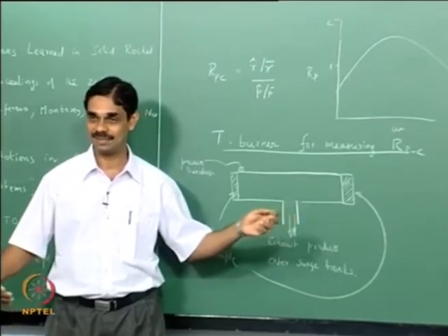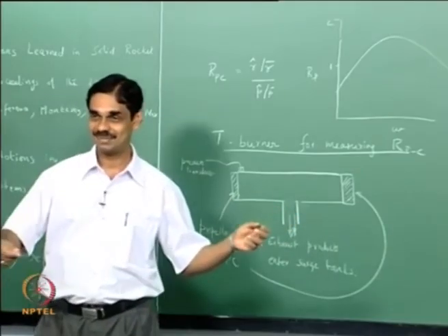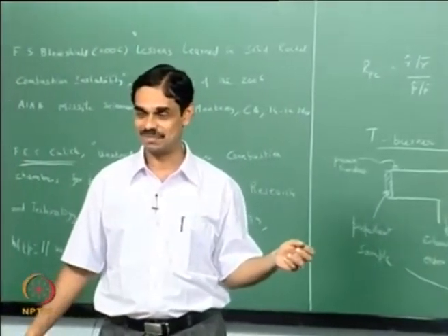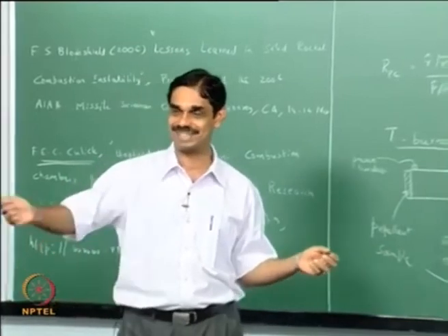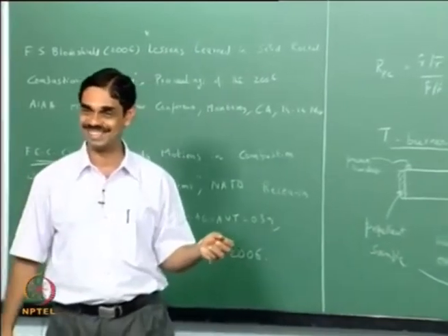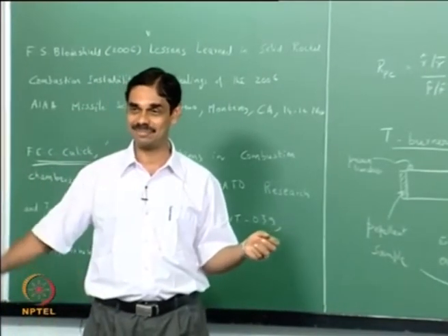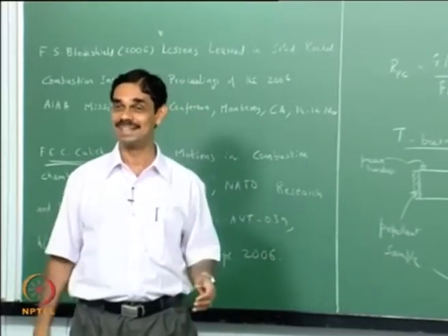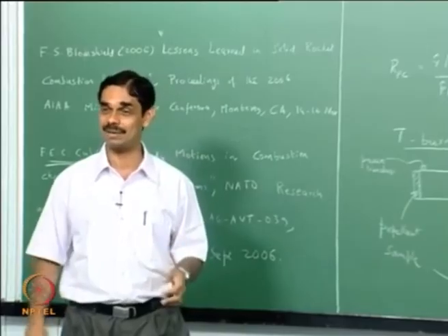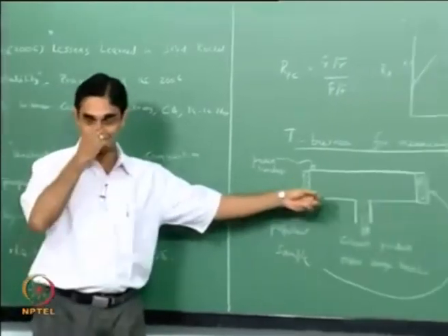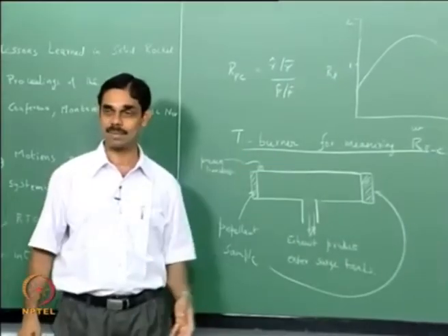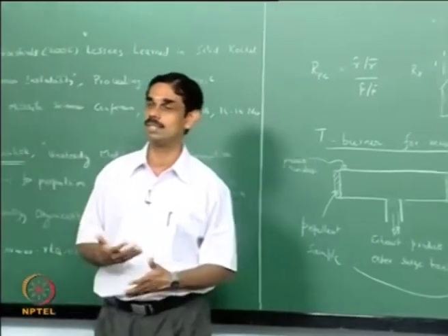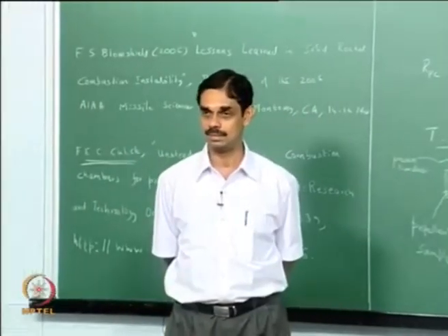So if your mom and dad are very rich, the expenses you make won't bother your financial status much, but if they don't have money, if you spend something today, your financial status will change dramatically. But if you are connected to deep pockets with your parents, then the money level you have with you won't change. So this is the same thing. You want to make the surge tank quite big, and there are some guidelines to that. Make sure that the mean pressure won't change more than a few percentage.